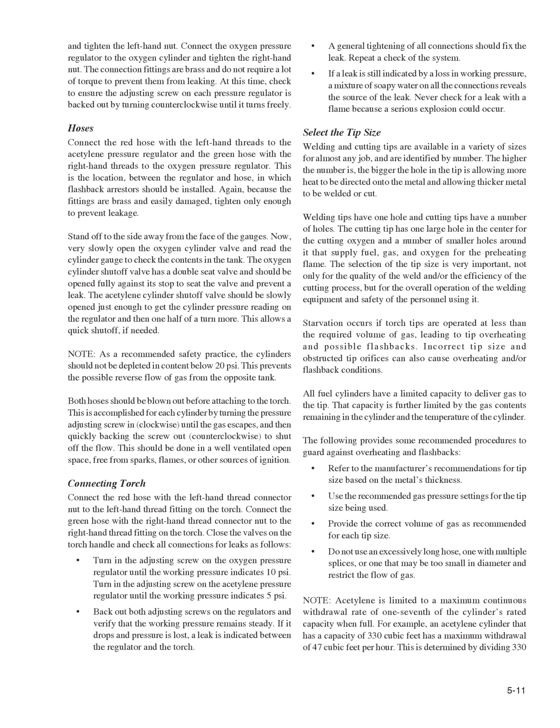Select the tip size. Welding and cutting tips are available in a variety of sizes for almost any job, and are identified by number. The higher the number is, the bigger the hole in the tip is, allowing more heat to be directed onto the metal and allowing thicker metal to be welded or cut. Welding tips have one hole and cutting tips have a number of holes. The cutting tip has one large hole in the center for the cutting oxygen and a number of smaller holes around it that supply fuel, gas, and oxygen for the preheating flame.